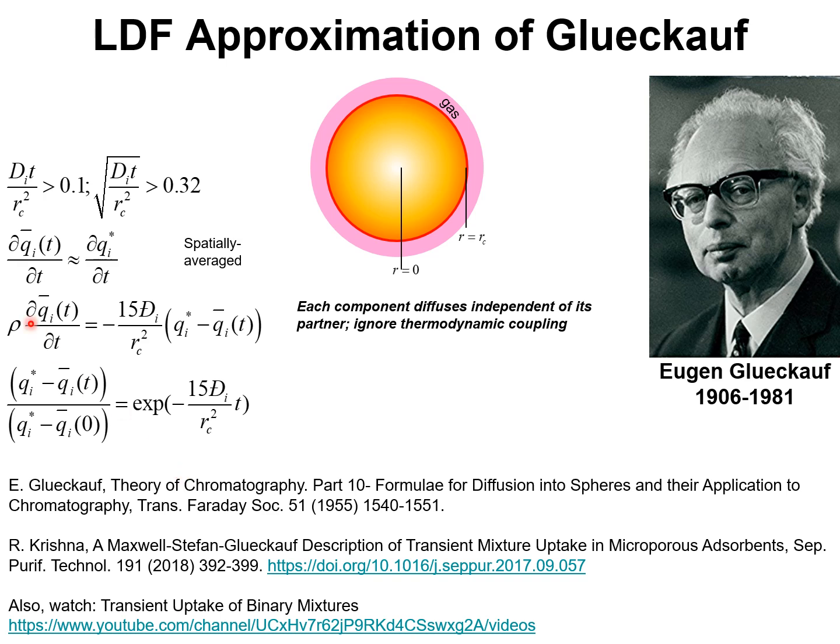Essentially, the time derivative of the average component loading is assumed to be equal to the derivative of the equilibrated component loading, and this equilibrated component loading is in equilibrium with the bulk gas mixture at that position in the fixed bed adsorber.